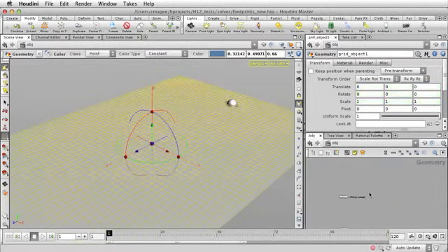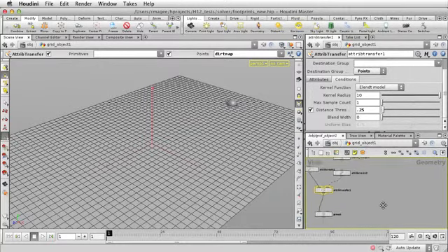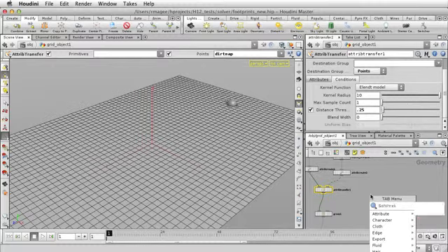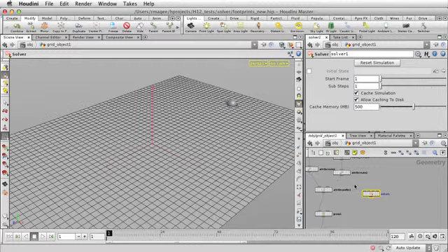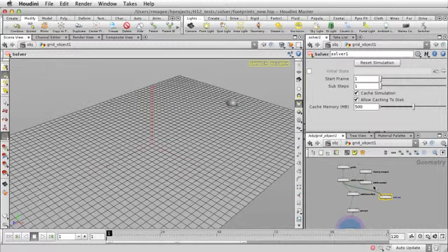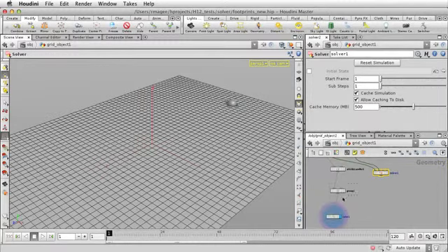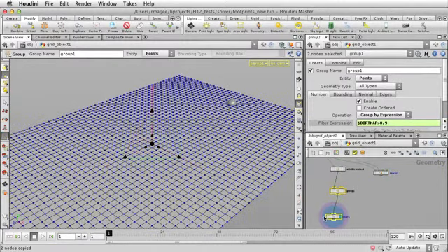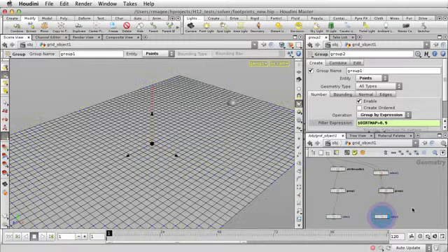And we're going to do that by going back into the grid object. And now, beside this attribute transfer, we're going to put down one of these new solver nodes, the geometry solver. We're going to click down. We're going to feed the grid path into the first input, and the attribute create from the object merge into the second one. We're then going to copy and paste the group and the color, and that will give us our new path.